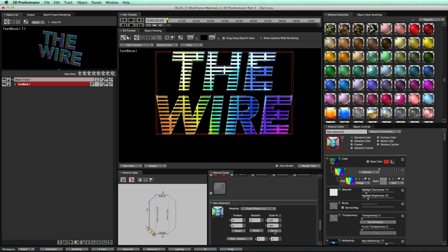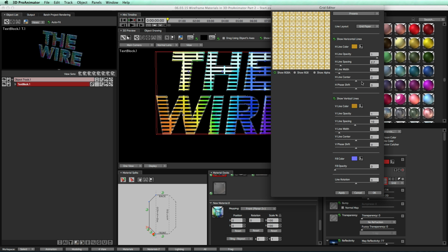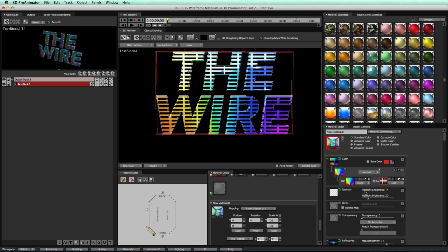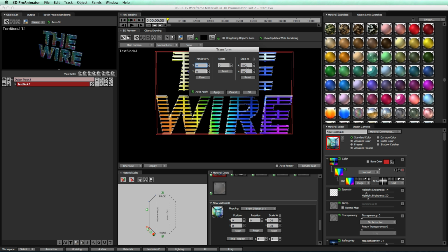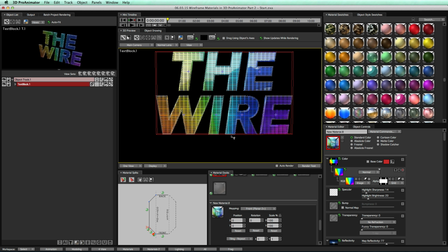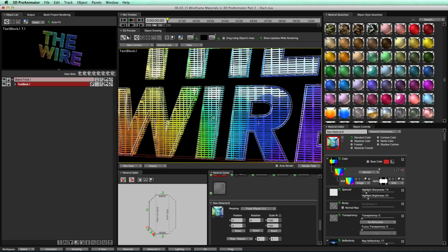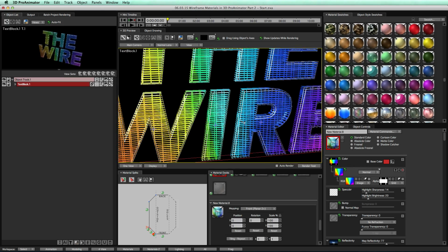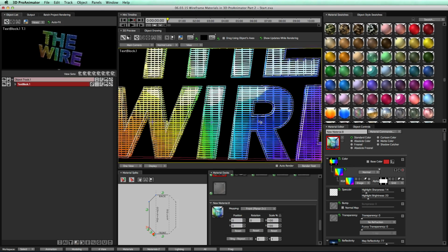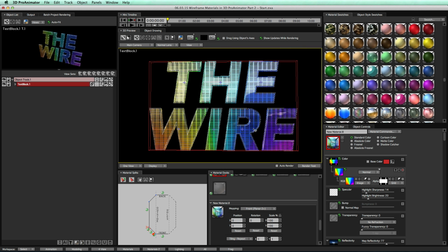So what I have to do is reset our scale and then come into our alpha grid and let's reduce, I'll hit cancel. Let's come over here to our alpha grid and take our transform and reduce the transform to something like 30% or so. Click OK, and now we have our one map across the entire material with smaller lines, just like that. Look at that. Very cool. All right. And we have our white outline that makes it look awesome. So once again, this was very easy to do. Makes it look really cool extremely quickly.